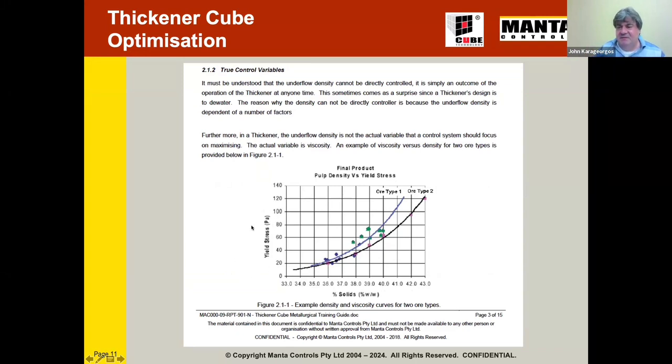And the problem with viscosity is, this affects pumping. So we have thickeners where the underflow is pumped, and some thickeners where it's gravity fed. As you thicken, depending on the mineral type, it's really important to know your viscosity density trends, because if you thicken to a certain point, you might find that pumps are struggling. Centrifugal pumps struggle about the 80 mark, and you can see this is real life data.